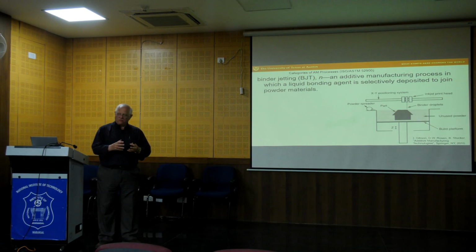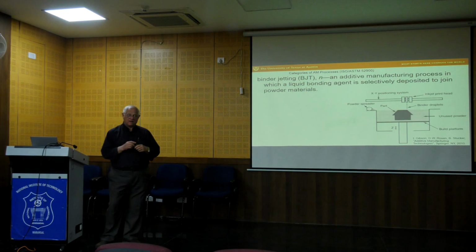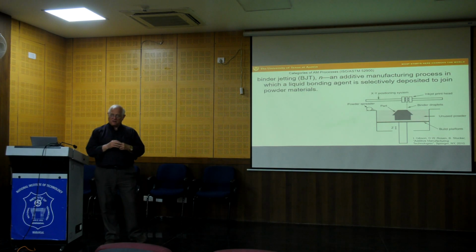They're very weak, as you might imagine, and so to get service-worthy properties, these parts typically go through a post-processing step where the binder is removed either chemically or thermally, and then at this stage we treat the part exactly like a powder metallurgy part with relatively low density, and we do the usual techniques to sinter the part together.